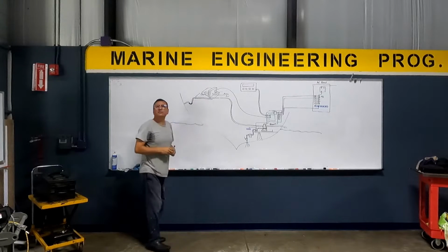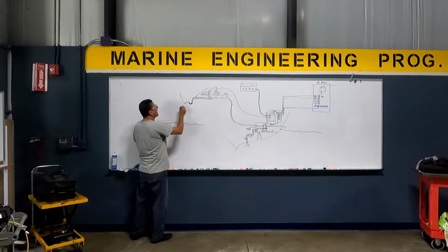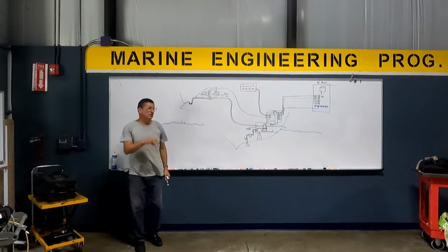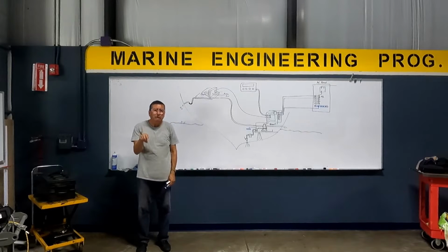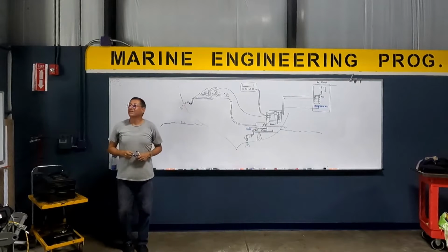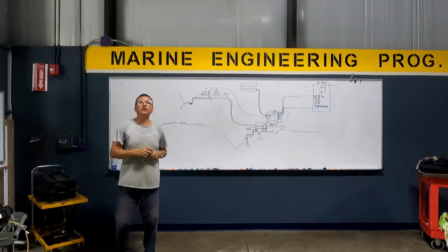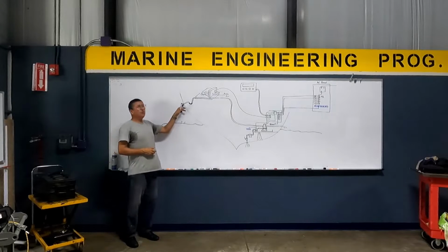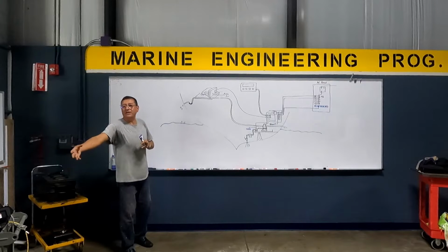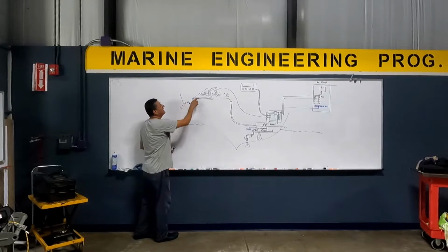That condensated water is what type of water? Fresh. It's fresh water, no? And that fresh water is going out here. That fresh water is not going at high speed. It's a little, no? What is this? Water trap. P-trap. Yeah, it's water. And the water produces a seal to avoid what? Water going back, forward gas. Those outlets will be close to the exhaust outlet of the generator or the exhaust pipe of the engines. That P-trap with water prevents the gases from entering here in the compartment.